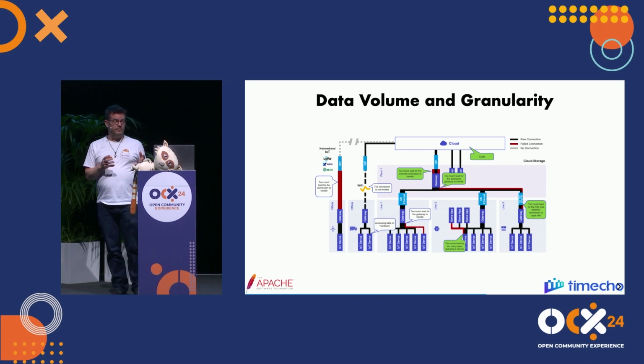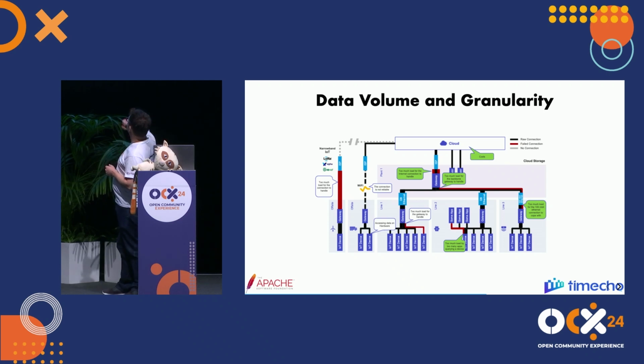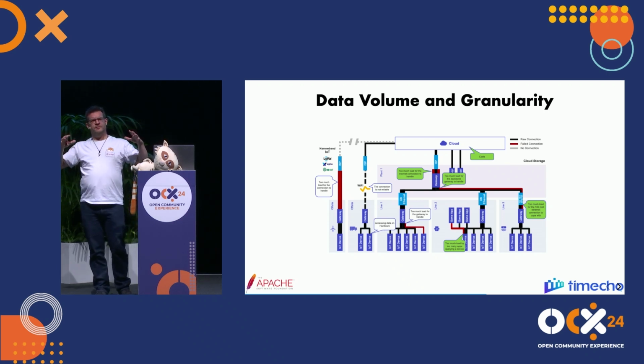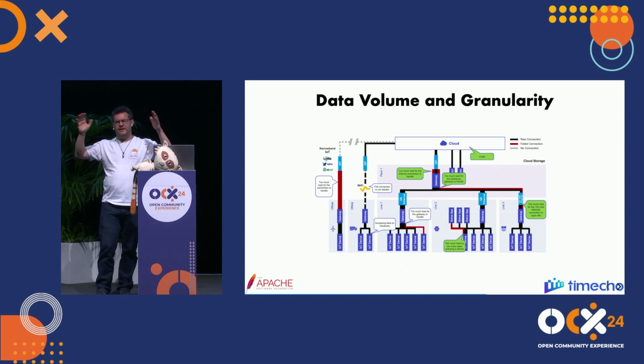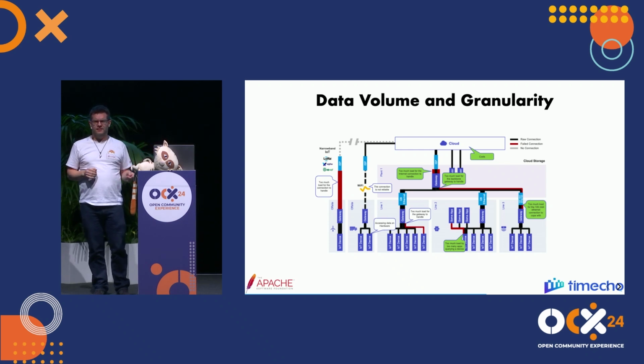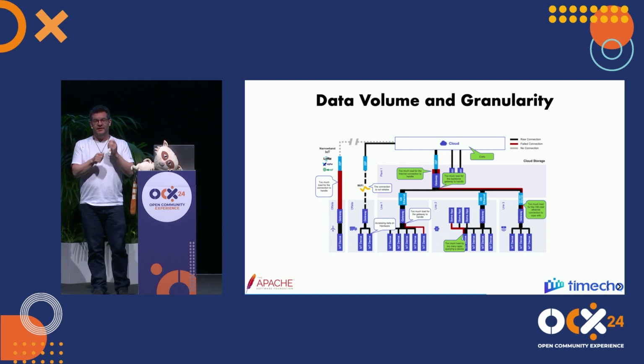Another problem is data volume, and especially the granularity. Let's start at the bottom. One thing I've seen quite often is you've got your production machinery, and it's controlled by an MES system, and it's working nicely, and then there's this new OT dashboard some department wanted, and they start collecting additional data. So they're asking the same PLC the same questions again.